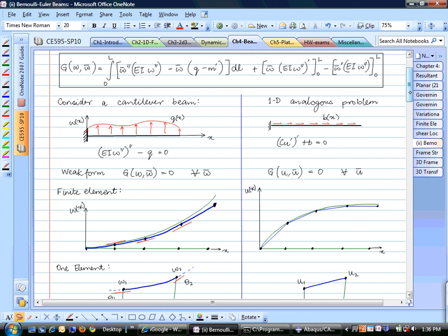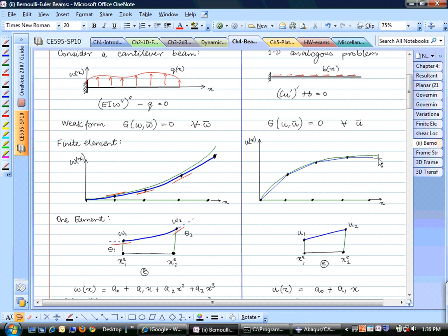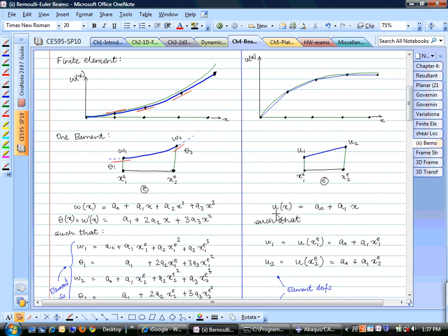Now if you remember, when we were talking about this as the solution, the way we constructed this was we said that we are going to assume that the displacement is linear within any element. So first of all, we took our domain and divided it up into 4 elements. And then we assume that the displacement is going to be linear within the element. And what that allows us to do is to write this approximation. This is very similar to the Ritz approximation, A0 plus A1 H1.